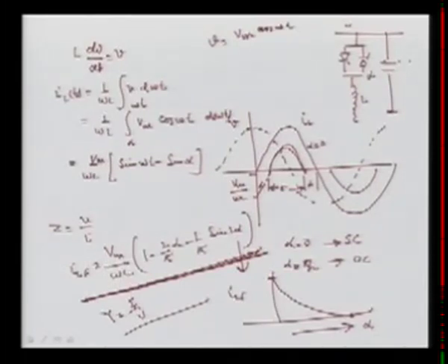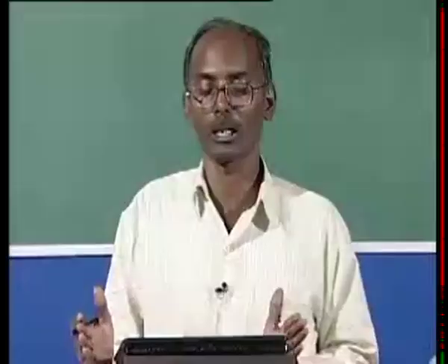So this unit is nothing but your thyristor controlled reactor, because the reactor L value here is controlled by thyristor, so it is a TCR, and here it is your fixed capacitor, FC. So this SVC is nothing but your TCR, thyristor controlled reactor, plus your fixed capacitor unit, and then we have to see the characteristic of this whole system.